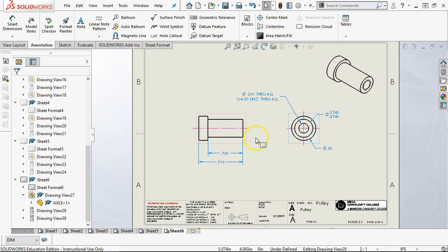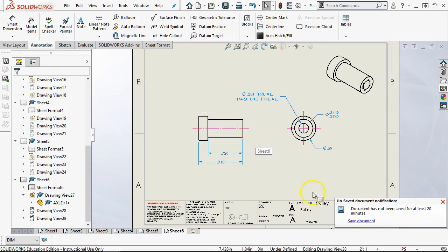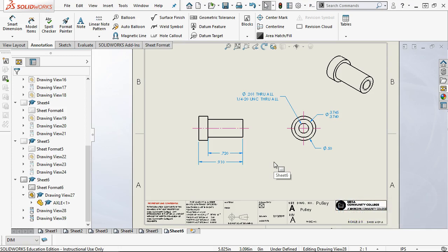All right. So the other thing is when we go to put the socketed cap screw in there, then maybe I only need, we're going through a 1/4 inch plate over here. And because this is just a retaining, I would like to have 2 to 1. I don't necessarily need 2 to 1 to the diameter of the thread, but it wouldn't be bad to have it.